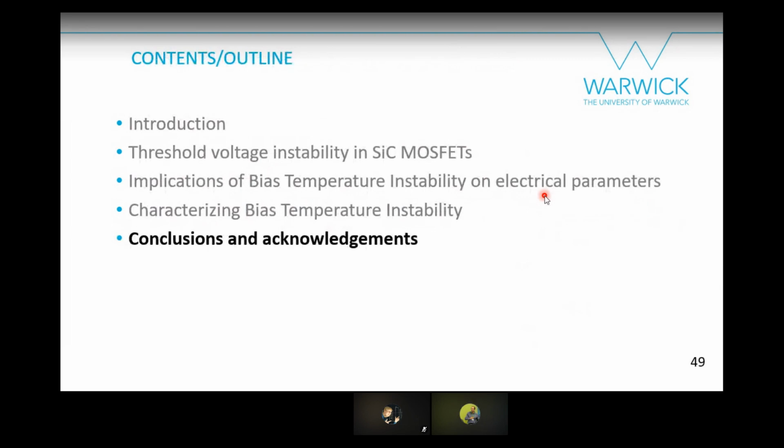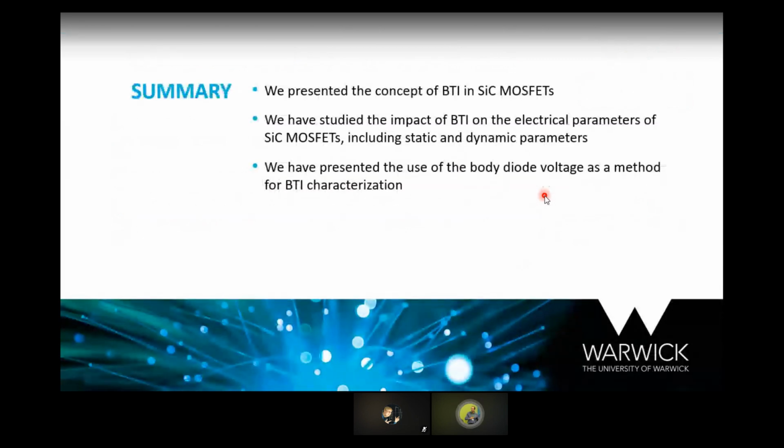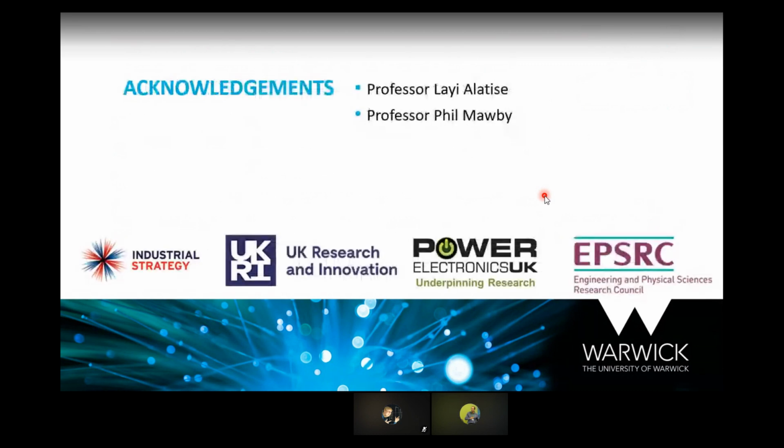So just concluding. We presented the concept of BTI in silicon carbide MOSFETs. We studied the impact of BTI on electrical parameters of silicon carbide MOSFETs, including static and dynamic. And we presented the use of the body diode voltage as a method for BTI characterization.